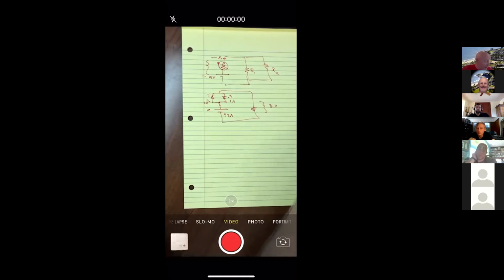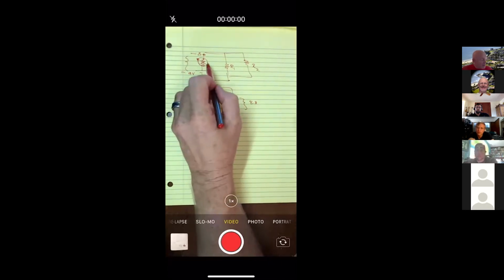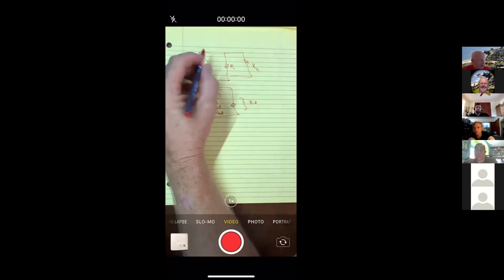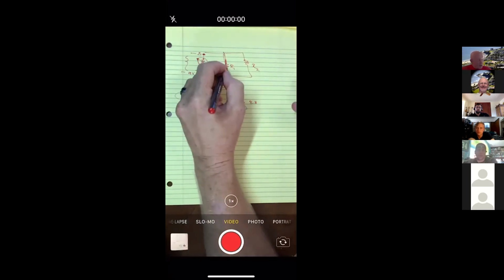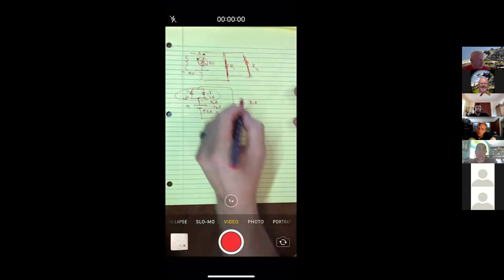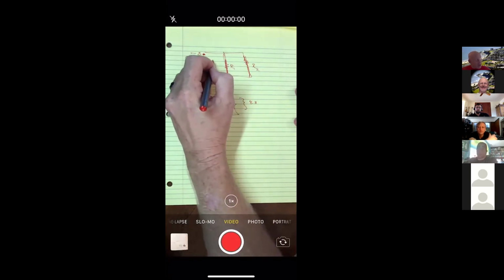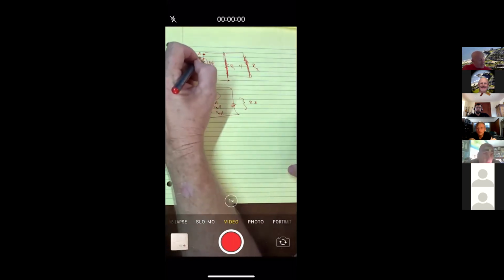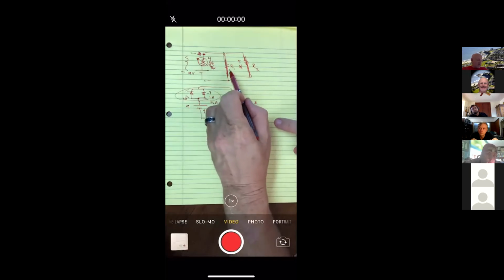But again, the neat thing about diodes is you just get 0.7, whether you put a half amp, a third of an amp, a quarter of an amp. So if you're building something like this and you adjust the potentiometer to eat up 4 volts, you only have 5 volts left from your 9 volts. But then you do the next experiment and hook up this. Once you do that, you're drawing more current, which goes through this resistor, which changes this drop maybe up to 5 volts, so now you only have 4 volts. Although then you could turn the potentiometer down so that this goes back to 4 volts and this goes up to 5 volts. So you just have to make that adjustment before you continue on.